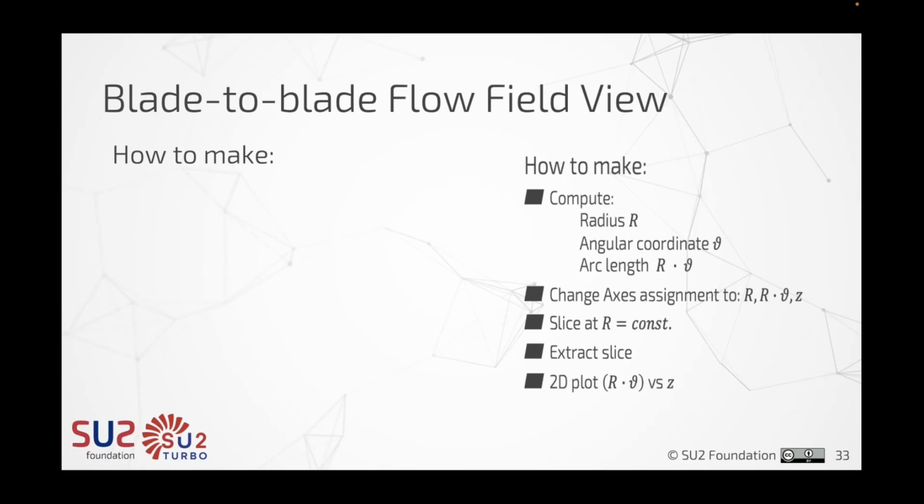Maybe the change in hardware made some tricks here. We should have just one of these anyway. Which are the steps that you need to take in order to extract these slices? Well, the first thing to consider is that Tecplot allows you to slice and extract with planes which are orthogonal to one of the 3 Cartesian axes.